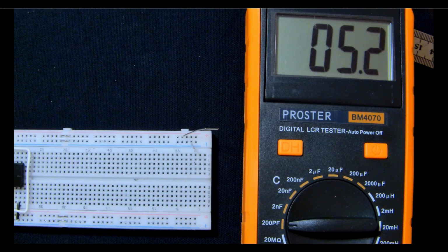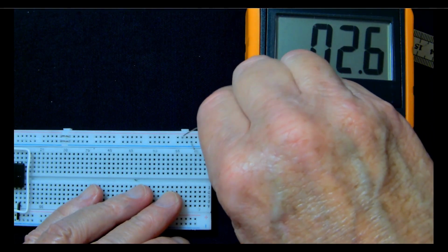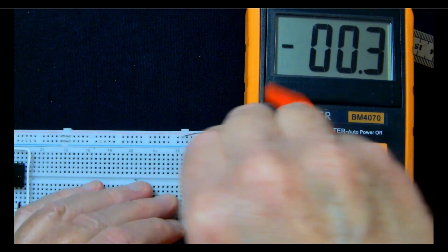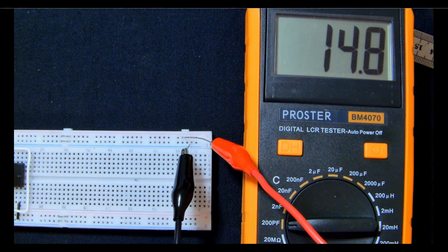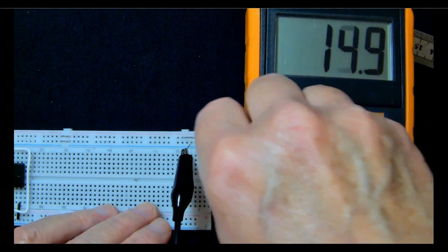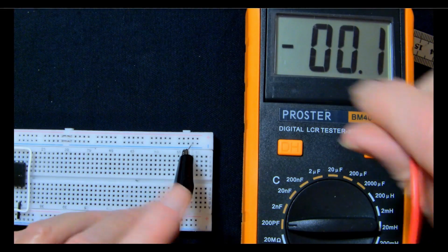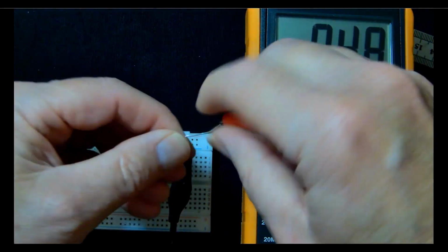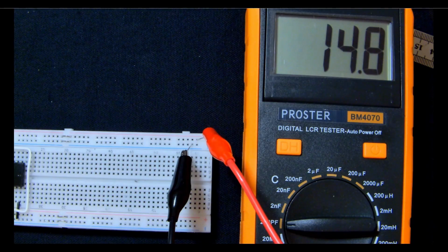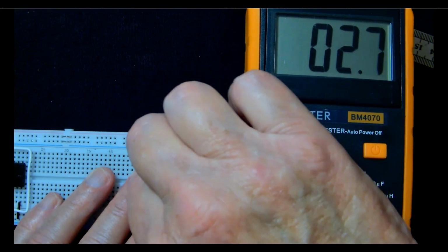What I want to do is put it across these two contacts, which I've got stuck into the power rail. Now the power rail's got nothing else connected to it at all, but it's still got 14.8, so that's interesting. Now if I short this out, just to make sure there's no residual charge in there or anything, that is still showing a capacitive value of 15 picofarads, which is quite high, but it's not unreasonably high.